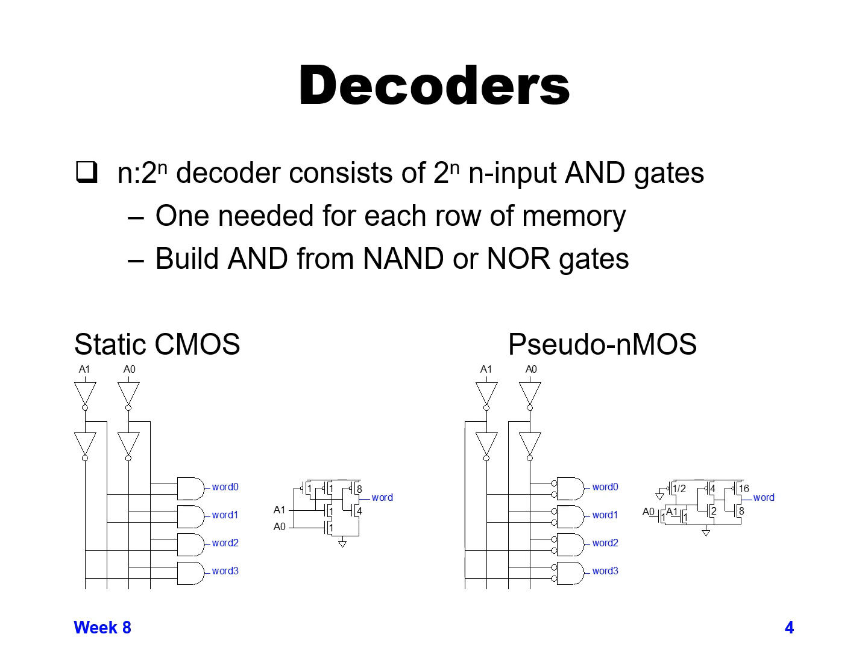In pseudo NMOS, we could design something where it's more like a NOR function coming in followed by 2 inverters, and having 3 stages there, you can get a little bit more gain in each of the 3 stages, and so you could have maybe a slightly larger output inverter. But again, I'm not a fan of pseudo NMOS, so I probably wouldn't do that, but there could be a particular application where it might come in useful.